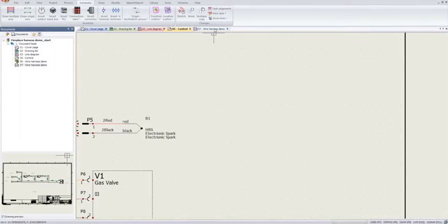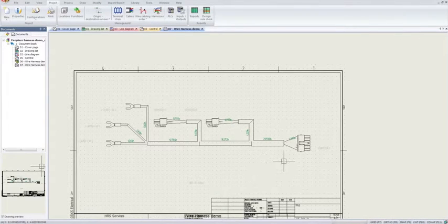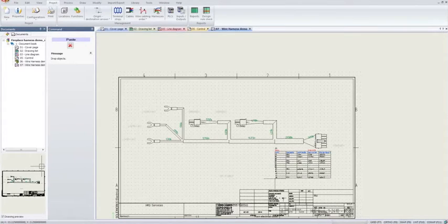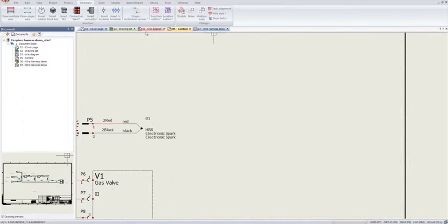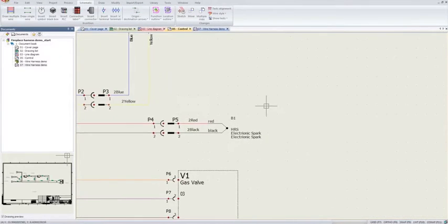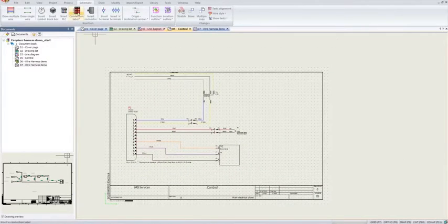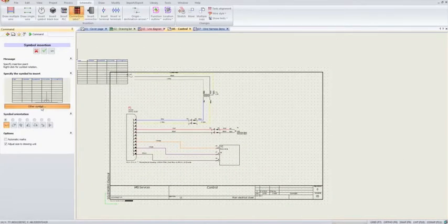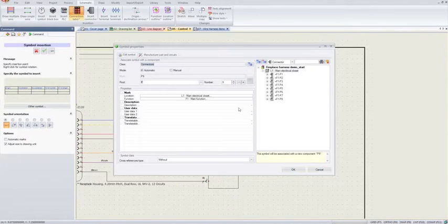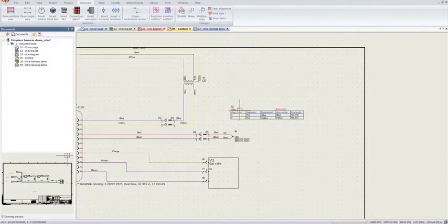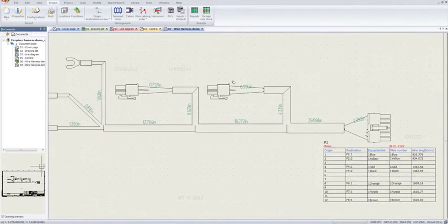I now want to put it close to the connector, so I'll go ahead and just cut and paste it into there, right? Reverse that process. Say I want to do one for the 2 pins, for that P2 and the P4, right? What I'll do is go to my connection labels. In this case, I'll use it for my 2-pin connector, right? I'll go ahead and place that in there, indicate, for example, this is going to be my P2. And then copy and cut and then paste into here.